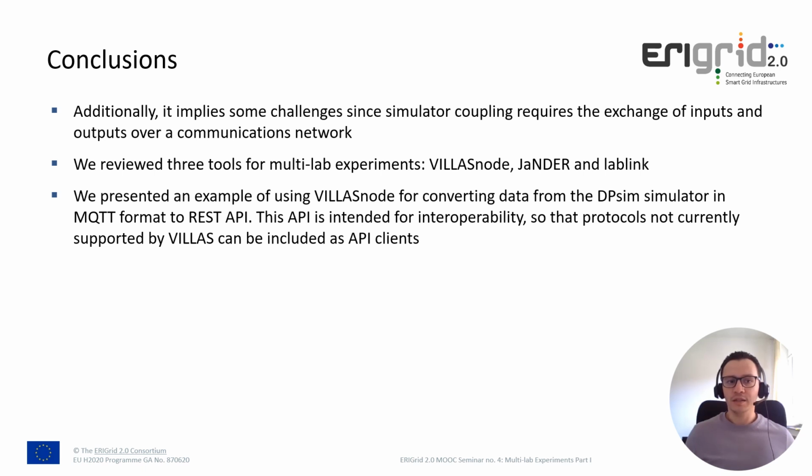For this, we need appropriate tools, and in this case we reviewed three of the tools for multi-lab experiments, namely Yonder, Villas Node, and LabLink. Finally, we presented an example of using Villas Node for converting data from the DPSim simulator in MQTT format to REST API. This API is intended for interoperability, so that protocols not currently supported by Villas can be included as API clients.